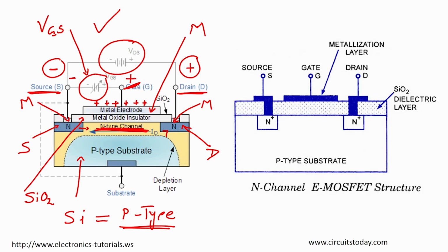Thus, this bridge is created so that the electron can flow from here to here. Also, this bridge is not made just for facilitating the electron to flow, it is also made up of electrons. So, these are all electrons lying in this fashion, so that now when I apply a source to drain voltage, which is positive towards source, negative towards drain, then the electrons will flow from source to drain and the current will flow in the reverse direction, which is shown by the blue arrow. Alright, easy, understood, very clear, right.